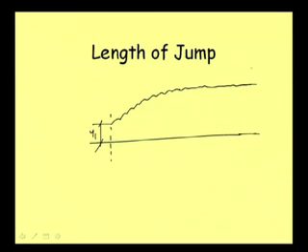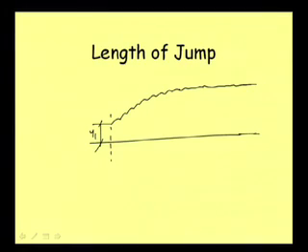If it is continuing with another profile, then of course it is further difficult to find the length of jump. For a practical experiment, we need to form the jump in a way that it is not continuing with another rising profile. If it is a falling profile, then it is fine. On the downstream, suppose there is a drop and then it is again falling like this, then it is easier for us. But if it is a rising one, then it will be difficult.